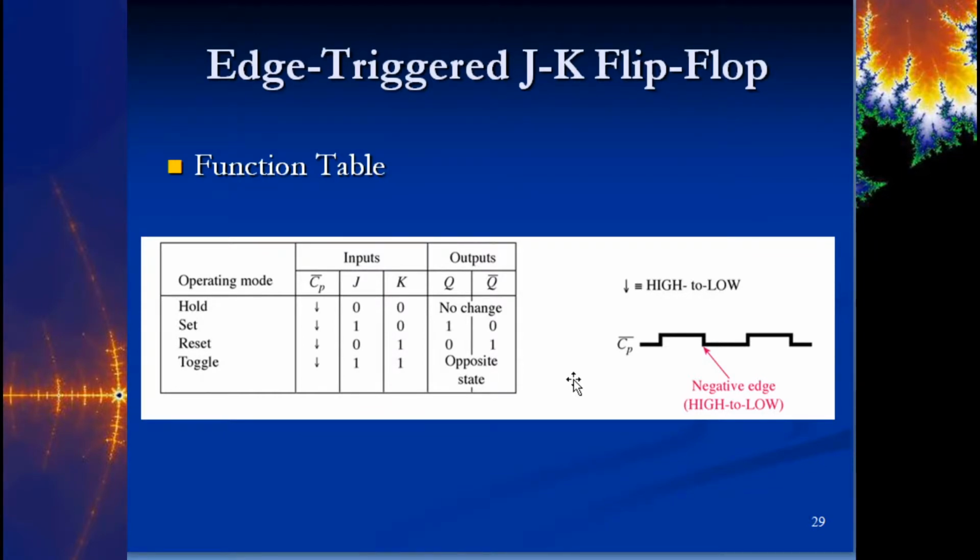So, if I have a clock pulse of 50 kilohertz, on my Q, if I have it in a toggle condition, it's going to be 25 kilohertz. So, you can kind of see where we would go with this eventually, where if you wanted to create a power supply, a 1 hertz, 1 pulse per second power supply. Well, you've got 60 hertz that's coming out of the wall, right?